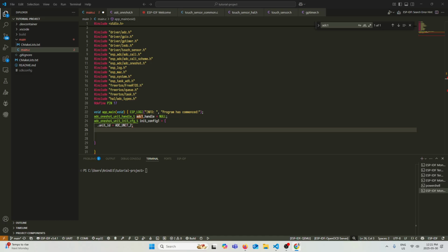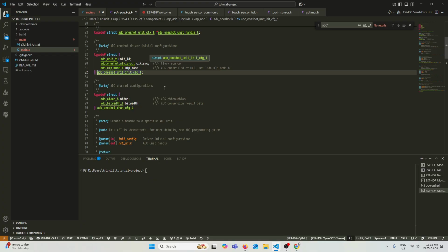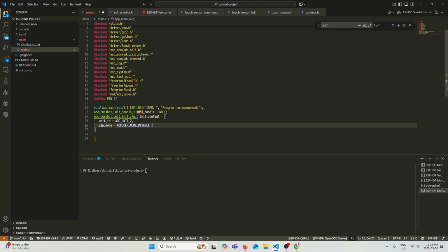Result in millivolts. The middle one wired to 3.3 volts. The middle one to pin IO26. Okay. And then we include the... Then let's do ulp mode. Clock source. So we don't specify the clock source. We're just using the default clock source.